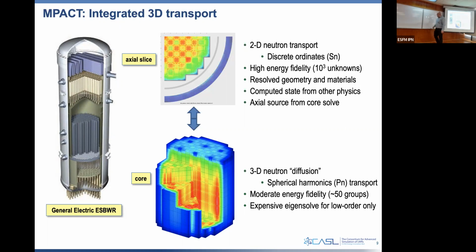Within each fuel pin, we're modeling explicitly the cladding and the gap, and we're putting in radial burnup so that we can have different amounts of fission products in each of those radial regions. Usually we're using 50 axial mesh. And if we look at the mesh for even just a single pin cell, our material definition is going to look like this, but then our mesh winds up looking like this.